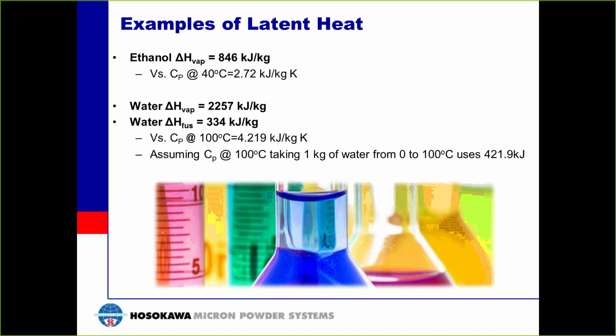So these are examples of the latent heat. For ethanol, you can see that example, and then you can also see how it compares to the specific heat. You can see that it's much higher. If you compare the latent heat of vaporization of water to the latent heat of vaporization of ethanol, you can see that water has a much higher amount of energy for the same amount of mass. This is per kilogram. So to take 1 kilogram of water from a liquid to a vapor is going to take a lot more energy than it is for that same mass of ethanol.